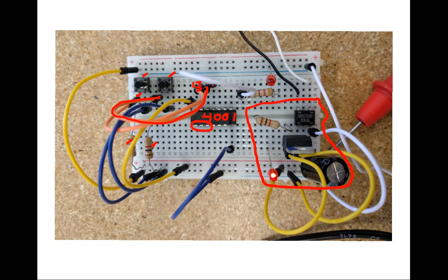And then the output goes up this white wire. It's kind of hard to see it. And then it goes through here, through the current limiting resistor, and then through the LED. And so you should be able to press these buttons and then look at the LED to see if it works. So remember, with the LED, you don't necessarily know which direction it is, because the LEDs are not indicated in the package.